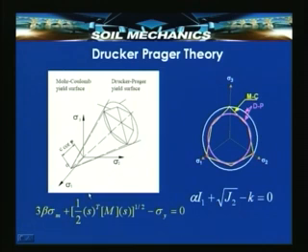Both Mohr-Coulomb surface and the Drucker-Prager surface are shown in this figure. The hexagonal surface corresponds to Mohr-Coulomb yield theory, whereas the conical surface refers to Drucker-Prager yield theory. In cross section, it will look like this, the hexagon and the Drucker-Prager circle. Now, do these theories match at all? How deviant are they from each other?